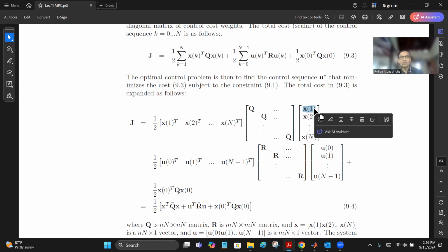And if you run this for 10 instances, at 10 seconds, with a control action every second, so 10 elements, and the state vector at every moment of time is 3 by 1, then this is 3 times 10, a 30 by 1 long vector. Then the second term, similar to that, you have u0 to un minus 1, whereas x goes from 1 to n.